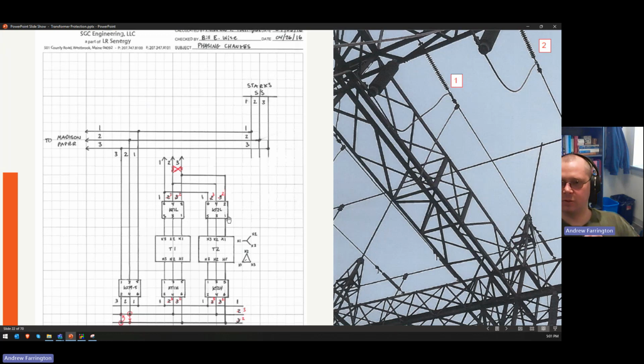And they said, no, that we can't use that switch because it doesn't phase. And so I was thinking that maybe there was some sort of rotation issue at the phase. They had brought in 1, 2, 3, and then 1, 3, 2 at the switch. So you can't close it because you tie 2 and 3 together on those two blades. And so you'd have to roll this here, and now it'll phase and everything will be fine.